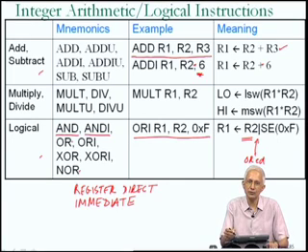Now, the notation used here tells you that since R2 is a 32-bit register, when the OR operation is done, the second operand must also be a 32-bit value. Whereas the operand specified over here, in actuality this is an 8-bit operand, but you know that all immediates in the MIPS1 instruction set are 16 bits in size. So, this is actually a 16-bit value. You can think of this as being the same as 0x0f, as many zeros as are required to make it into a 16-bit value.